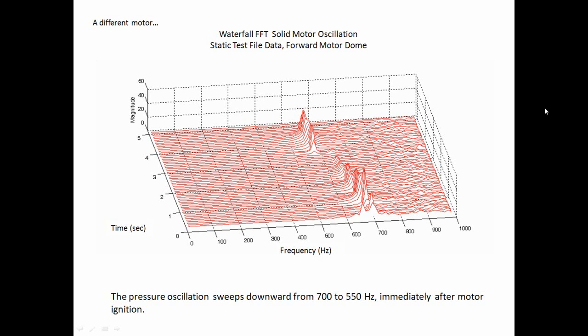So again, avionics need to be designed and tested accordingly. And when avionics components need to withstand these sorts of sinusoidal oscillations, a good engineering practice solution is to mount them via isolator grommets, because the isolator grommets can do a wonderful job of filtering out this high frequency energy.